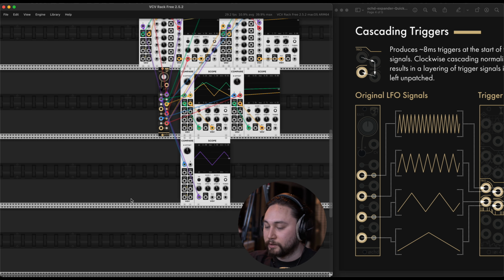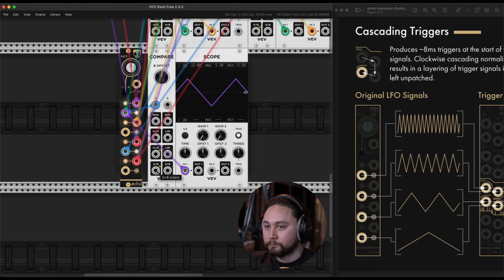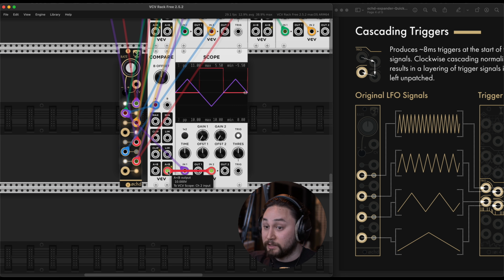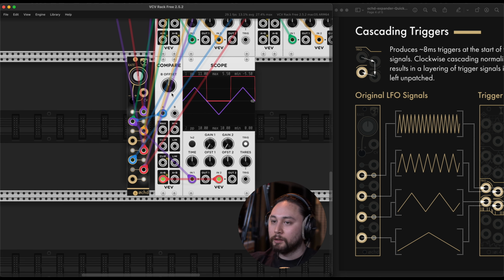Let's view this triangle wave. And let's view this output. So that's when A is less than B, when A is higher than B. So this is a pretty common way of extracting a square wave from a bipolar periodic signal. This is just a comparator. So anytime the A signal is higher than a threshold, the threshold being 0 volts, the output logic is high.